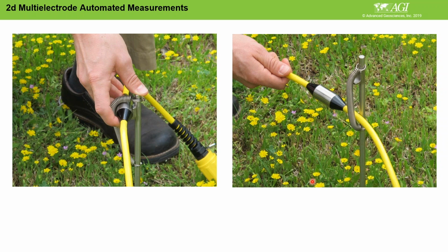Depending on the area, this sometimes gives some error. Sometimes corrosion, especially on alligator clips, also increases the contact resistance. Some people connect directly with alligator clips, but I have seen them get loose sometimes. But you can decide whatever is convenient for you.